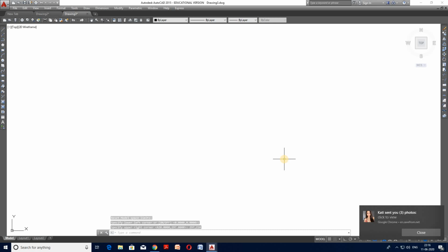Now how will you display it on the screen? For display you have to draw a rectangle of the same size. So by using the rectangle command, the shortcut is REC. See, this is the beauty of AutoCAD 2015 or the latest versions of AutoCAD 2000 series, wherein if you type that particular keyword, it will automatically list all the different commands associated with that keyword. But if we compare with the older version of AutoCAD, that is 2007, this facility is not there. So enter REC.